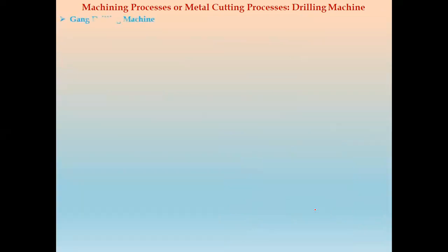Now next, the gang drilling machine. For workpieces which require several related operations, such as drilling holes of different sizes, then reaming, boring, we use a gang drilling machine.